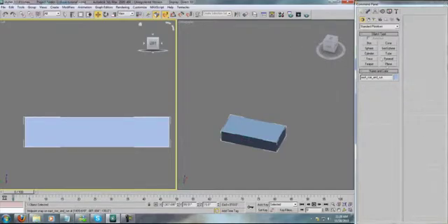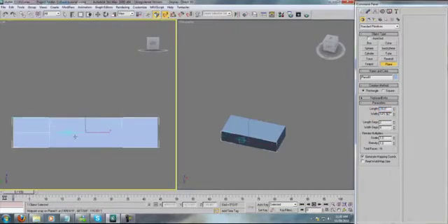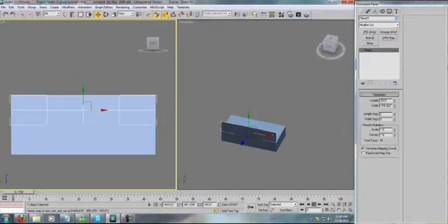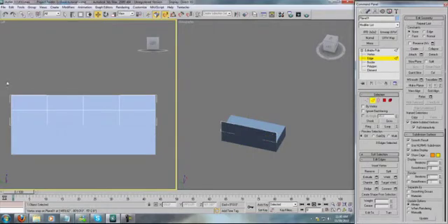Now since our railings are going to be the same length as this, I'm just going to create a plane that's snapped to that length automatically. We want to set our height to 3. We're going to have 4 sections, so that's set correctly, and then 2 rails, one at the top and one at the middle. So we're going to have 2 length segments. Let's just snap it up here, convert to editable poly, and bring our sides in.